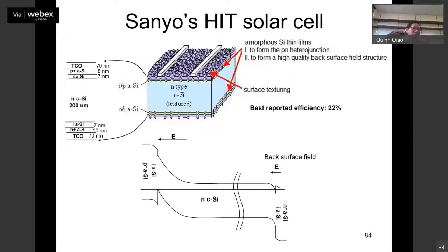Then there are other solar cells, HIT solar cells. That's basically where you do a lot of texture structure on the top contact, and also you deposit amorphous silicon here. The only difference is you have this P plus on the top, right? Because this one is a crystalline silicon solar cell. Okay, this one is different from the P plus we talked about before. The structure here is N plus. Okay, the wafer, the substrate, is N plus, different from the conventional one.